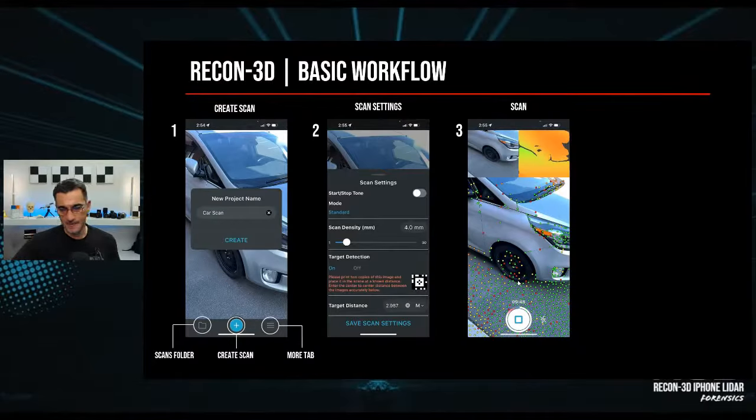But basically, you'll see that this is the screen here. You get a number of points that tell you the strength of the feature points or triangulation, and you also have the depth map up here too. I start looking at that more often now when I'm scanning. But that's what you do. Then you hit the record button at the bottom, this big button, and you start and stop from there. When it comes to recording, there is a maximum 10-minute limit, which is quite a lot.